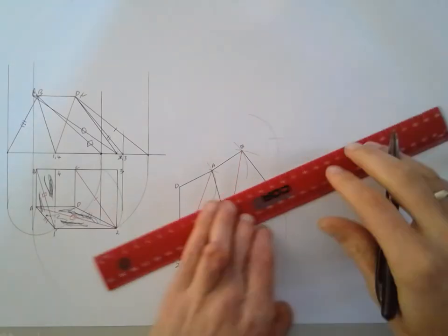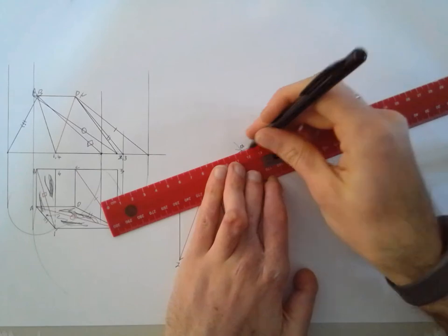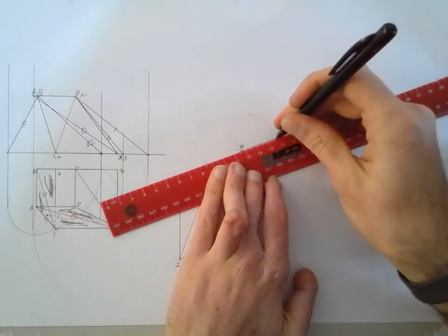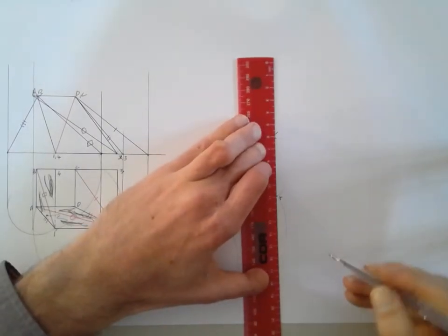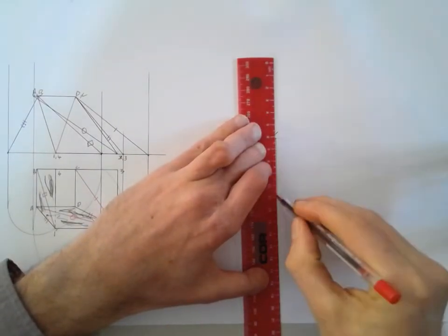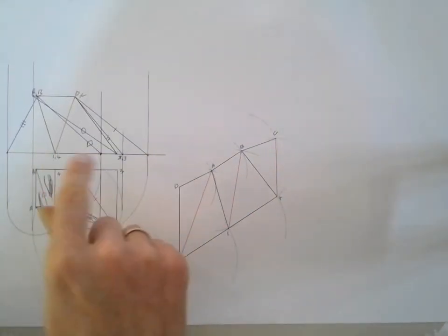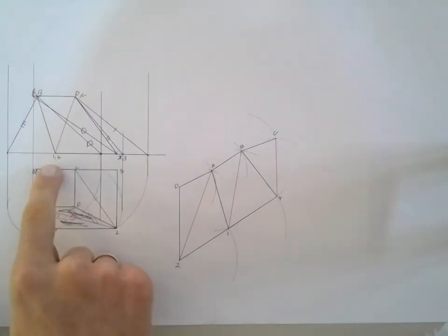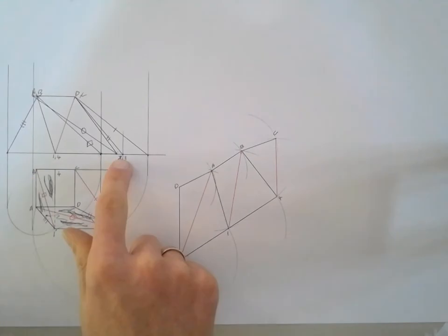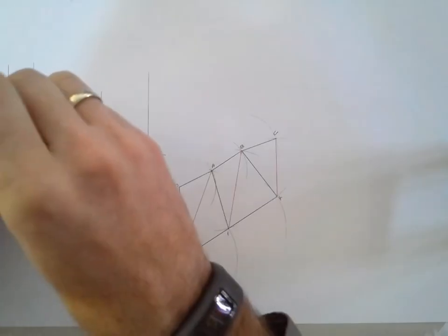And then you're going to join up B to that point, so that is now point C, and the line from C to 4 is another construction line. Then the next part of the triangle is then your triangle from point C to 4, and from 4 to point 3. Okay, so we need the true length of line 4 to 3, which is in the top view.